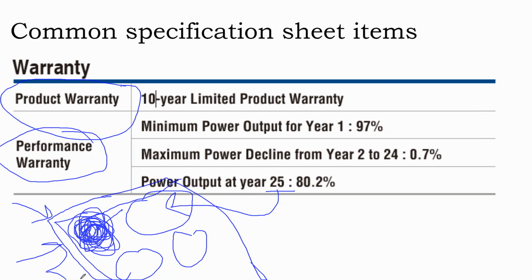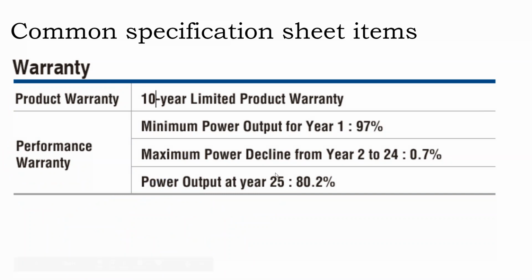And so the manufacturer is trying to split those differences to say, I'm vouching for the quality of the panel and I'm reflecting that in my cell warranty, but I'm only going to give you a 10-year warranty on everything else about the panel. And so you have to watch out for that, because that's a common misconception, that the solar array has a 25-year warranty. That warranty is less comprehensive than you might think at first approach.